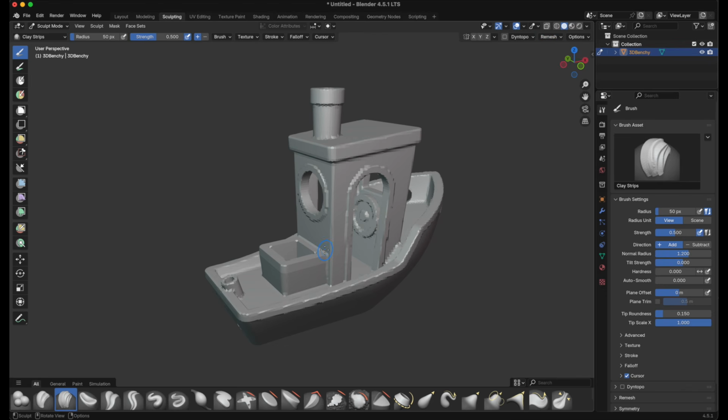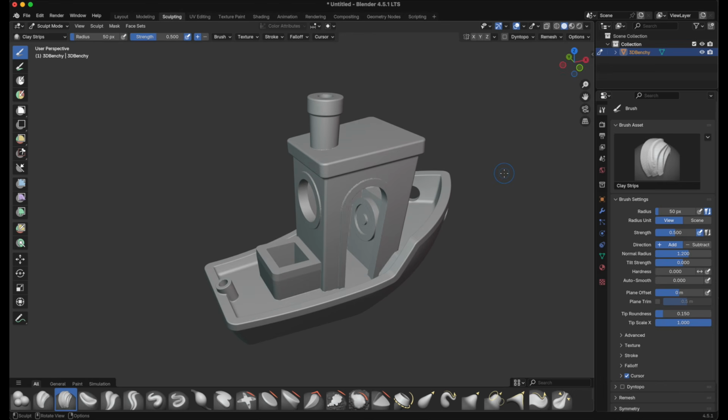The resolution's getting better, but it's still not high enough. Okay, let's go down to 0.1 and remesh. Now the reason I start with such a big number is because you could create millions and millions of polygons, and it will crash your computer. It'll basically just freeze Blender. So make sure you start big and go smaller.